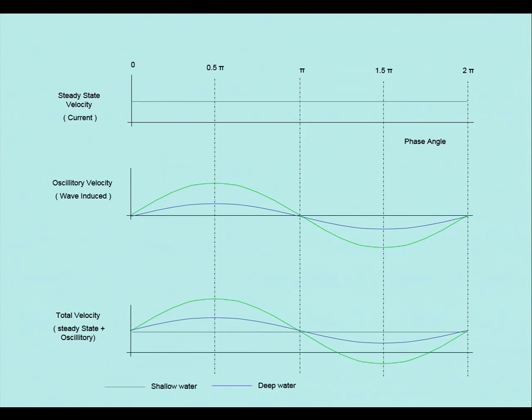But, so, we take currents to be tidal, steady state. As you know, at certain times when the moon and the sun pull together, you get spring tides and you get the higher velocities, you get the higher forces. But it occurs twice a day. So it will only peak for something like 6 hours, twice a day. So therefore we take it to steady state, we assume it constant.